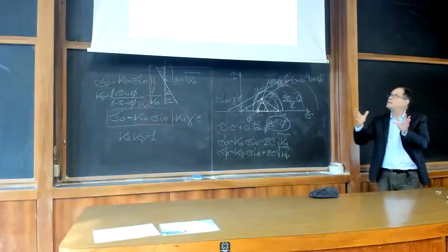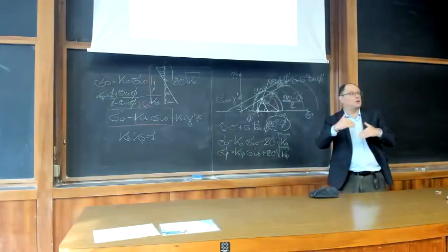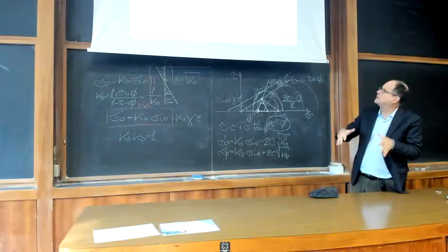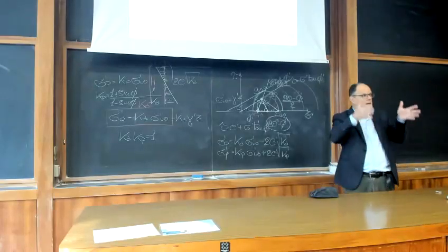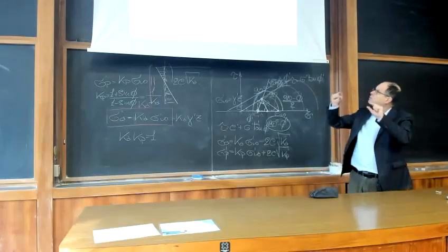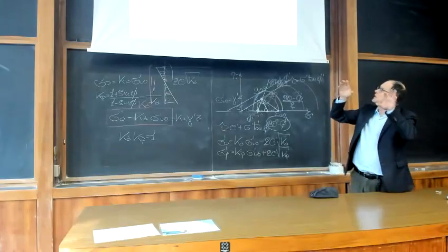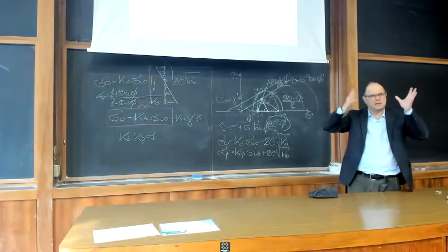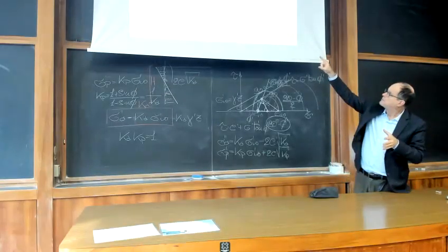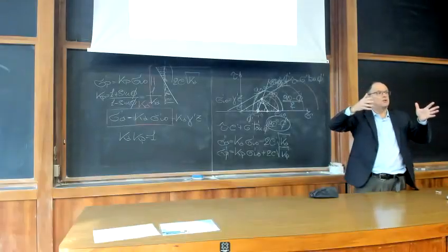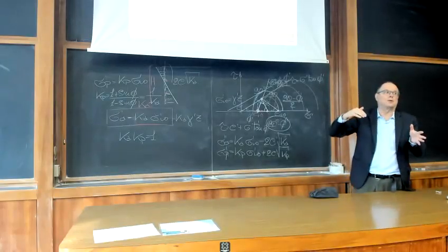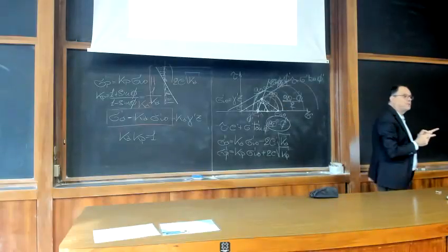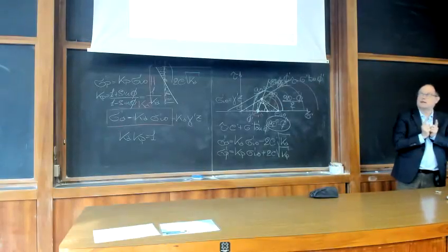And the way it interacts with the soil is through the bottom of the foundation. We neglect what happens along the sides of the foundation, which is very small. Typically the soil around is a remolded soil, so we typically neglect the lateral interaction between the foundation and the soil.